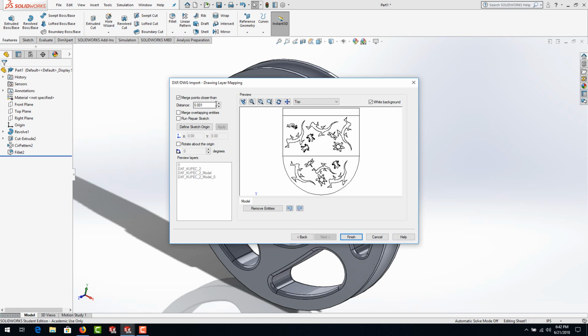Well, early versions of the software where people were learning, like, for example, the Autocads or whatever software they learned back in the 80s and or 90s, they didn't always learn the right methods, or sometimes even the precision of some of the earlier CAD systems was so low that perhaps the lines didn't meet up. And draftsmen were being converted to CAD detailers, and they didn't realize that you had to zoom up on things to actually lock them in correctly. So older drawings might have that issue.